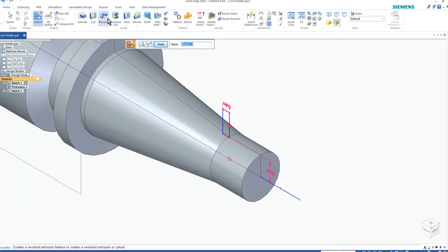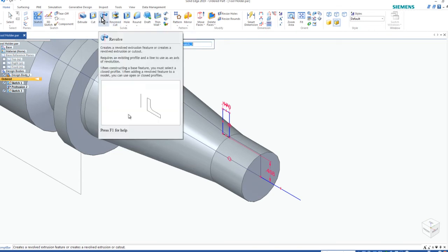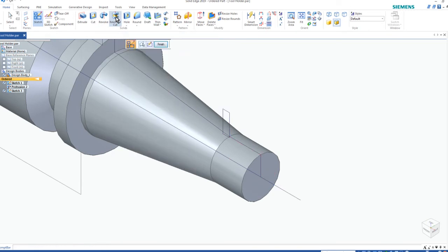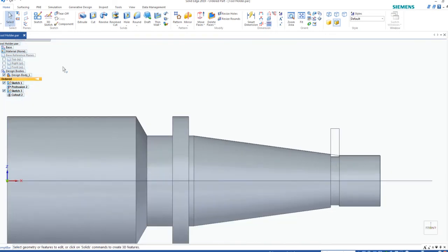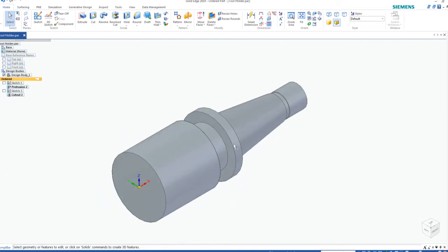Okay. Now, what we're going to do then is we're going to use not the revolution, we're going to use the Revolve Cuts. I'm going to click on Revolve Cuts, select that shape, accept it, select the line, and then the donut, and then click Finish, Cancel, and now we have our little cut. Okay. All right, let's continue forward. As always, what I like to do is turn the sketches off, that way it doesn't distract.